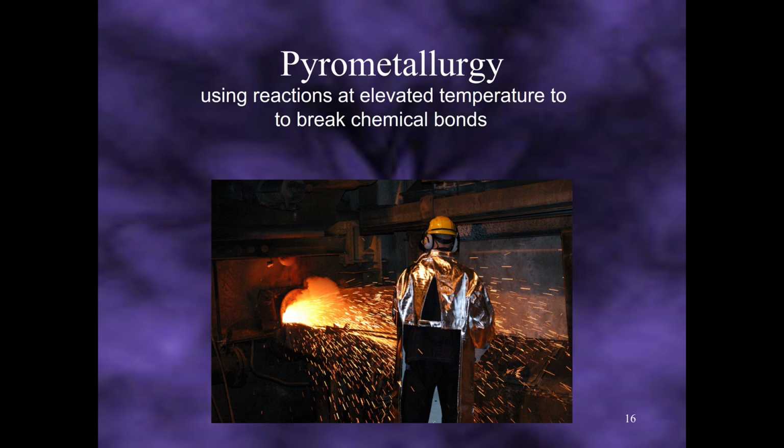So, as a reminder, hydrometallurgy was about conversion of minerals which are produced after the mineral processing step, at low temperatures in wet mode, to produce metals eventually. However, pyrometallurgy is not a wet process. It is high temperature, or sometimes we call it dry processing, by breaking the chemical bonds and producing the metal of interest. In the case of iron, we talk about smelting, but some other pyrometallurgical techniques are there. For example, calcination.